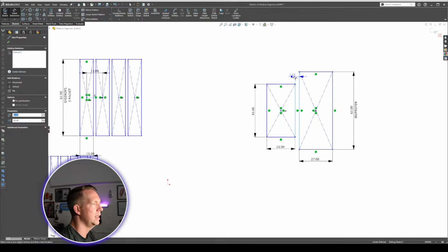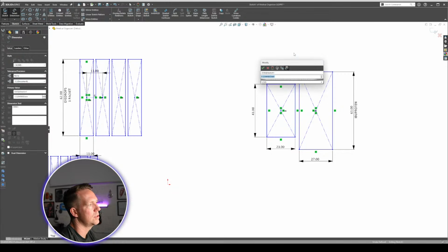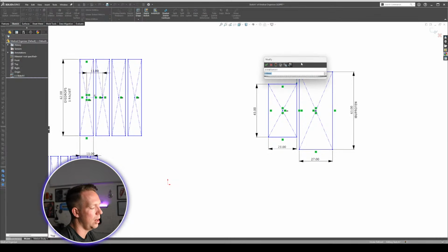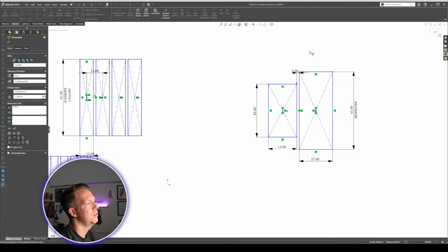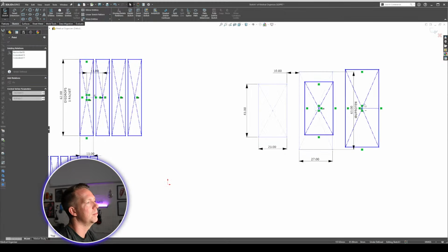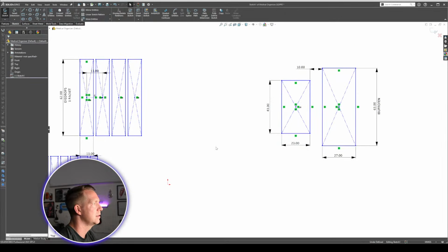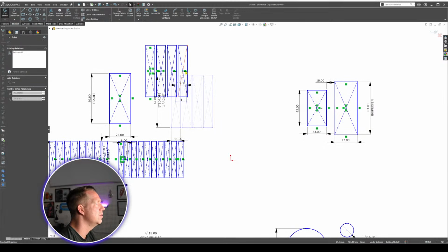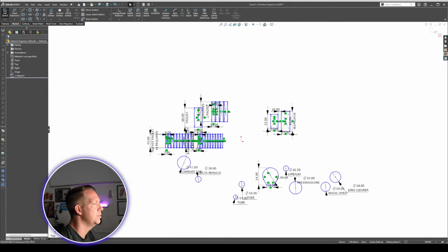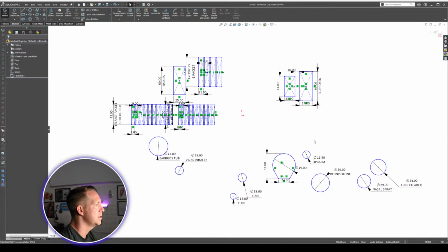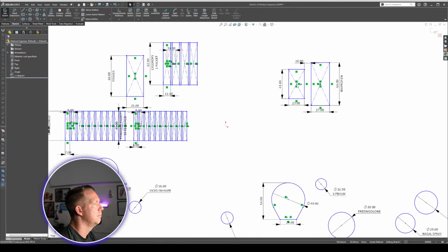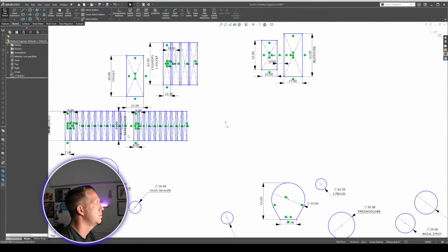And if I want these two to be linked, I can put a dimension between them. So let's say, do I want 2 millimeters here, or because they're separate items, do I want to give them a bit of space, like 10 millimeters between them? But now those two are linked. All right. So as we start to add more of those, we can start to link more of our objects together and progress that spacing. I'm just wondering on the best way to do that.